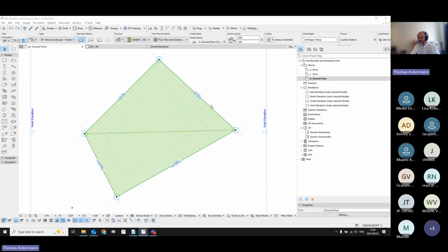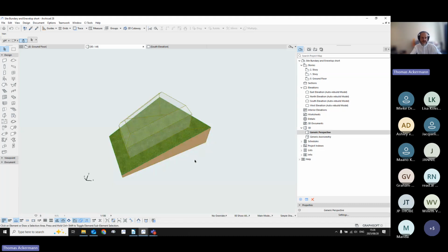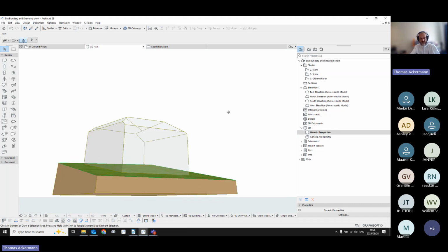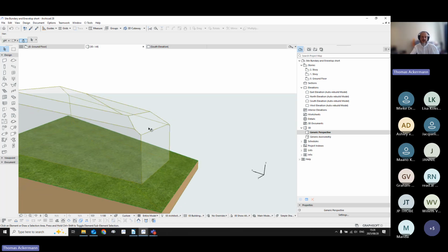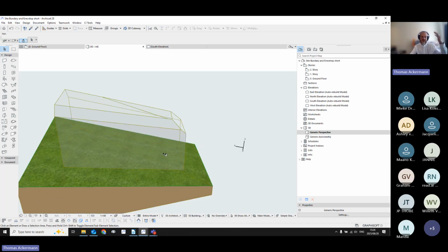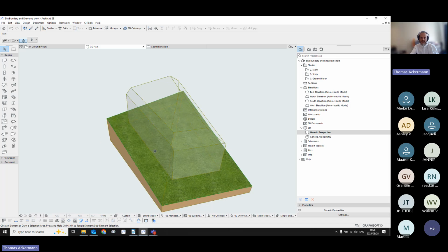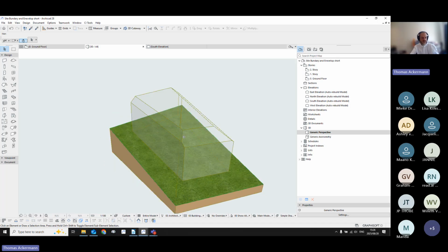Place building envelope. There's a rolling height restriction that you can put in, not 50 meters, 5 meters seems normal. And once that's placed, we've got a building envelope that respects the site boundaries and also respects daylight angles. You can obviously make those daylight angles 0 if it's just having to follow the mesh, and it will duplicate every single contour that you have on your mesh onto this. You can see the diagonal contour running over the top there.